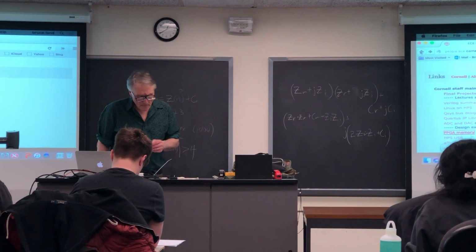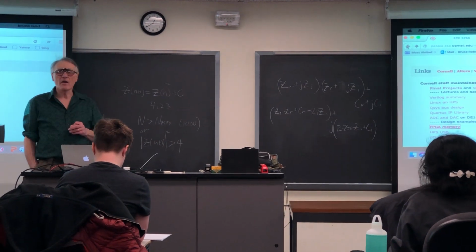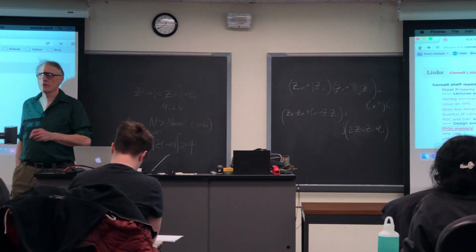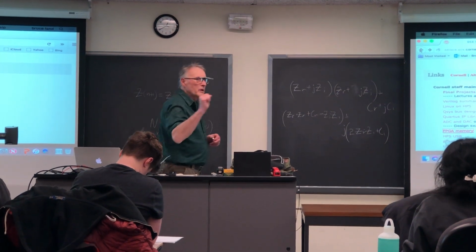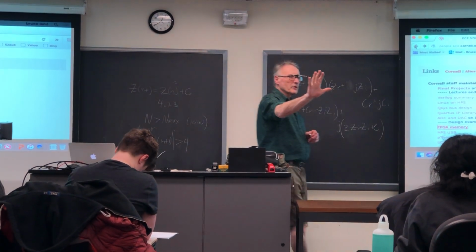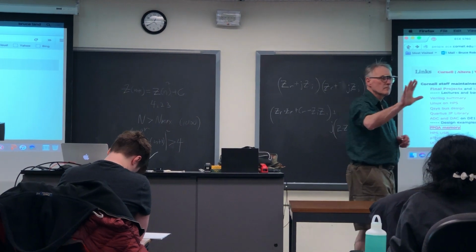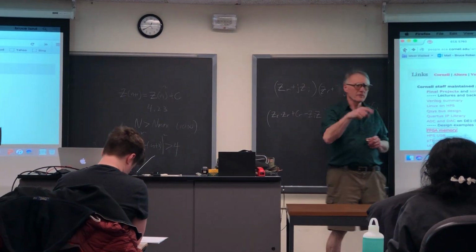So we need 5 multipliers per iteration. At one extreme, you could use 5 multipliers and do it all in about 2 cycles. Or you could use 1 multiplier and do it in 5 cycles.